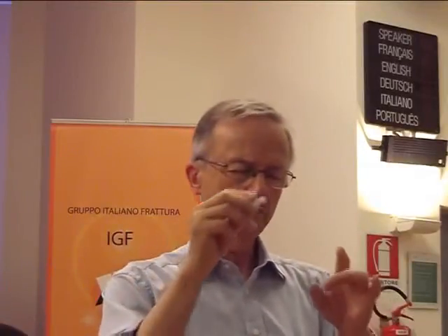We talk about plastic limit load, which is a mechanical quantity. It should be limit force. That's why I introduced in our methods the term force with the symbol F. And F, not P. F is standardized by ISO for force and not P. And that's why I also said the yield F sub Y is a yield force. Your load is not only misleading, it is wrong. Full stop.